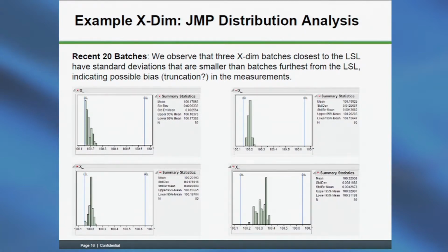And we've emphasized with the technicians making the measurements to be accurate, but this is something that happens in industry, and unless you've actually gone in there and physically observed them, you don't realize that this can happen. When measurements get near the reject level, the lower spec limit, they tend to put a little bias in it.